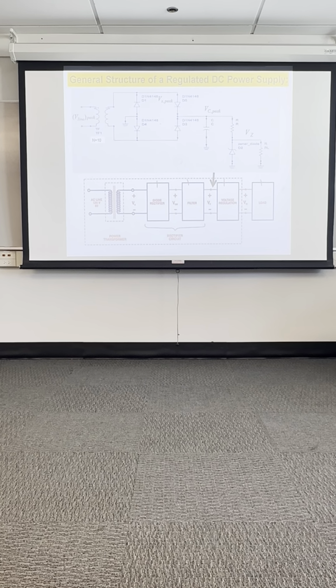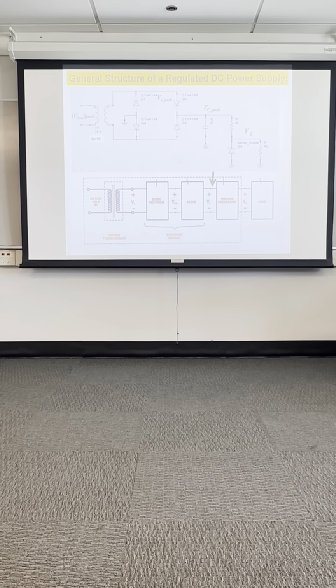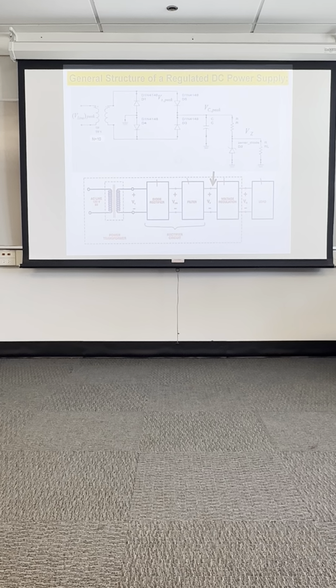We covered rectifiers in our last session. What's the name of this rectifier? There's four silicon diodes. It has a single capacitor. Here's our zener, and here's our zener resistor, and then there's a load resistor connected to it.